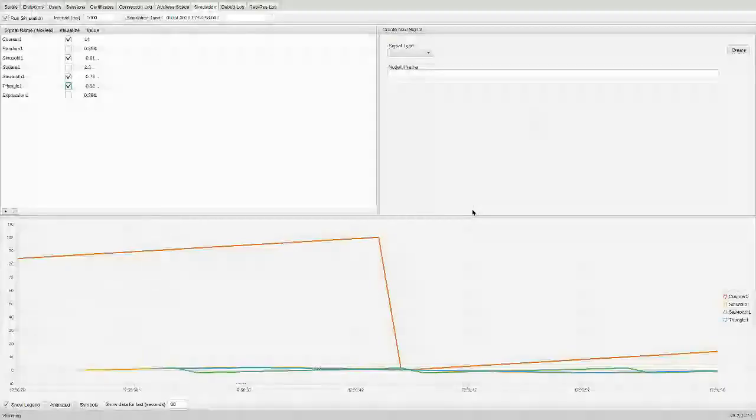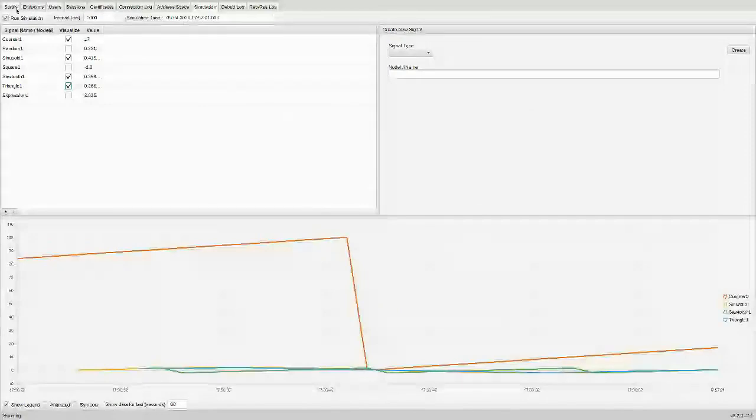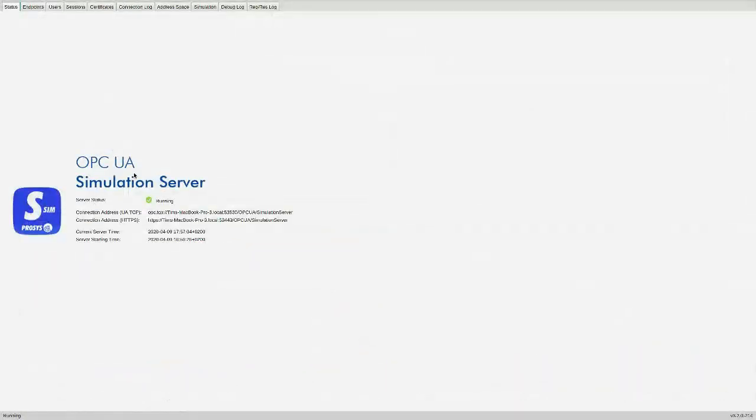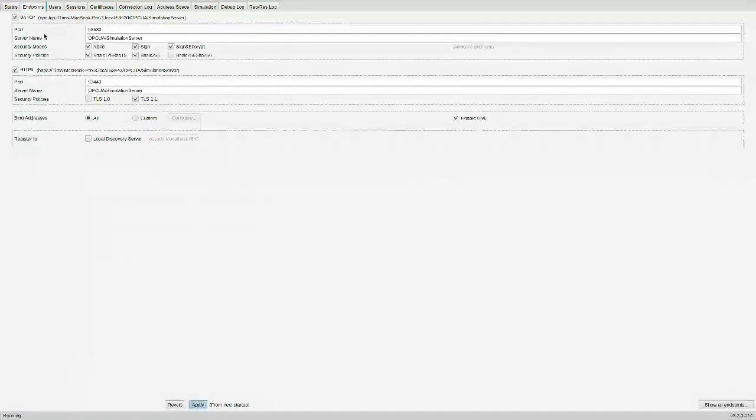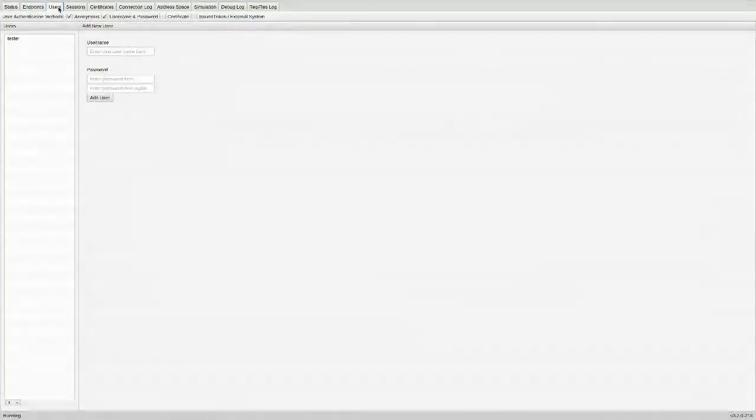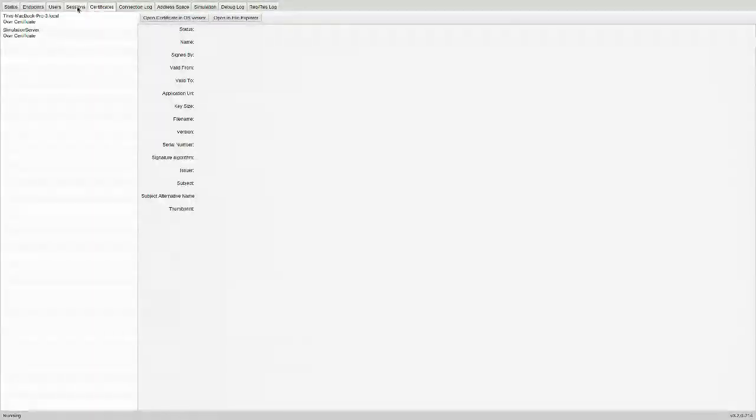Thank you. So, as Julian told, we are using for this demonstration this process OPC UA simulation server, which is free to download and free to use for testing and stuff like that. So the good thing is that it usually supports any operation which you can imagine due to OPC UA servers. So you can adjust different endpoints, security modes, also user access. We just entered here, this is the user tester. We just entered with a password. But you can also create some certificates for that.